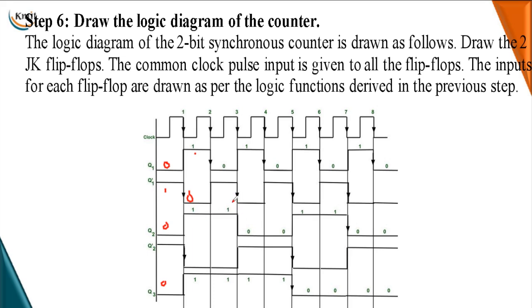Now at the second clock edge, my previous state is at logical 1 and the input applied to that flip-flop, Q1 bar, is logical 0, hence it will not be toggled and will continue in its previous state as the present state. But when I come to the third clock pulse falling edge, your Q1 bar is logical 1.